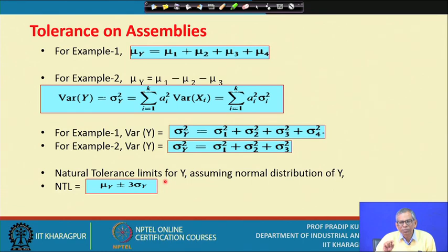Now when you get a process to achieve this target, the process condition is varying, and you are affected by many types of factors. But what you have mentioned is that at least I have made the process controllable. That means the process is in statistical control. That means the process is affected by the natural causes. If you refer to the different kinds of patterns we have discussed, it's a natural pattern. So that's why the term natural comes, and that's why these tolerance limits which you get are referred to as the natural tolerance limits. I think the logic is made very clear.